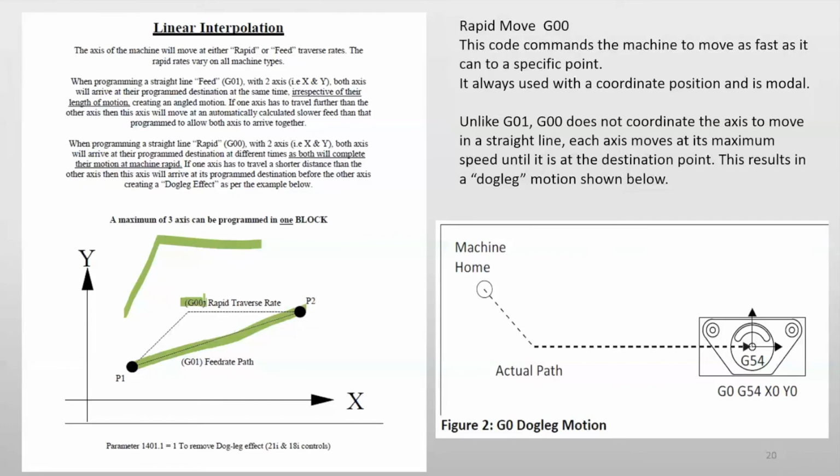And the reason, if you know it, is that the way you program is a 0 and 1. And then when they build the computer, because they go with G01, G02, G03, they had to have that digit. But these days, G0 does the same thing as G00. Great. So that's the other thing.